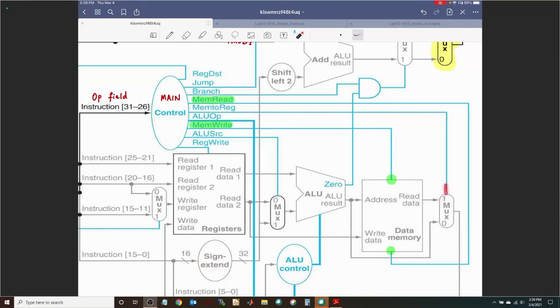So the mux control would need to be 1, versus if you were, suppose, doing an add instruction in which you would never have to do a memory access. What you would do is you would take the result of that addition operation, and then you would let it bypass the memory and then write it into the register file. So the memory to register is to pick up one or the other. I can also highlight that in, say, blue. This guy is for here.